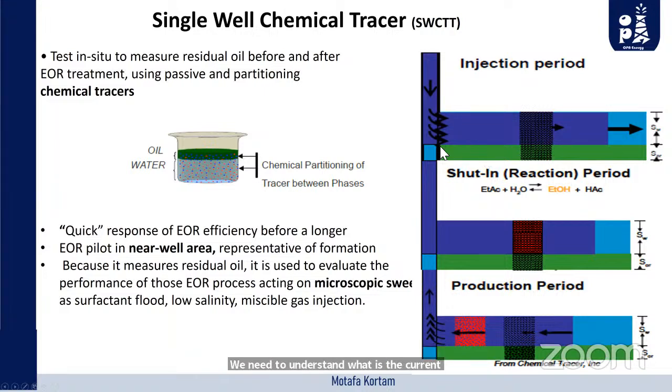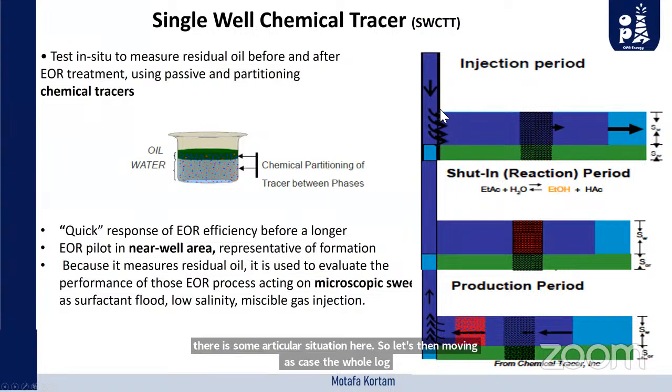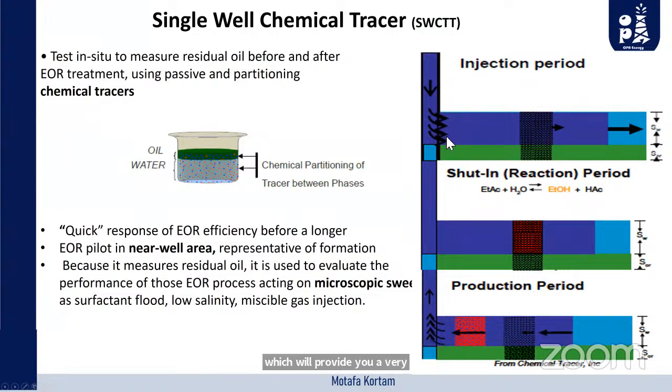You usually produce the well, and the water cut moves, so there is a particular saturation here. Rather than running a cased hole log, which provides you a very short distance around the producer well, just a few inches or maybe sub-feet, this will provide you a bigger area on how the residual oil is within the reservoir around the well.